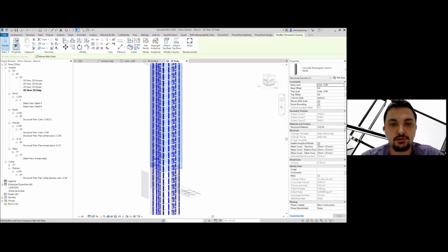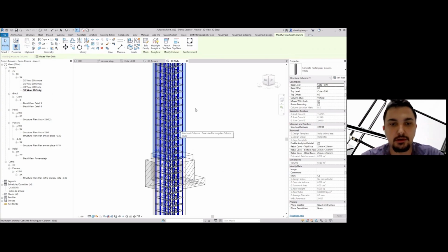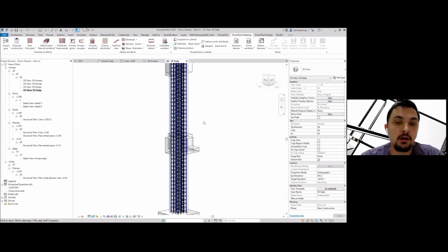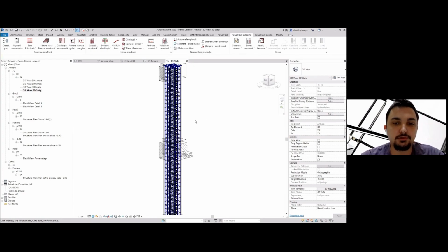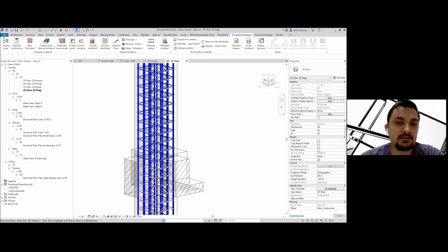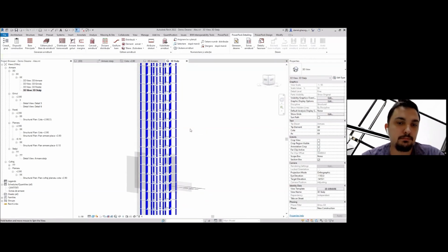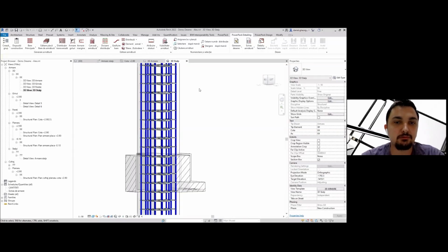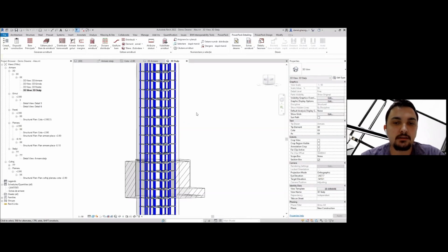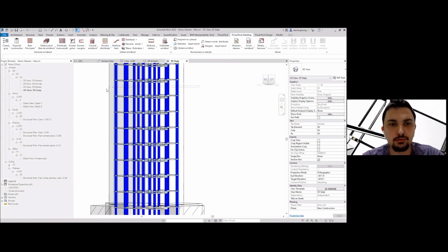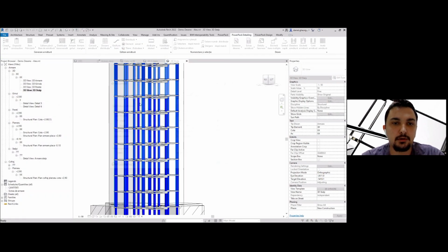and of course you need to split the rebars at the top of the first column. Now, what you should by default do, you should basically change each rebar set in this column. We sped up the process a little bit, and we developed a crank tool that will automatically crank the rebars in order to avoid some collision.